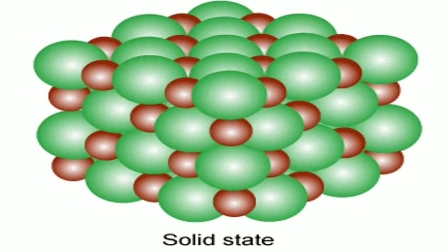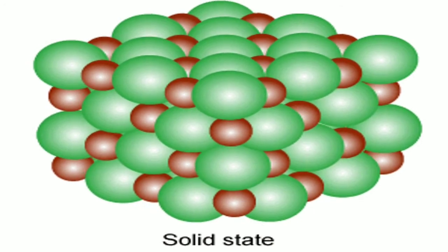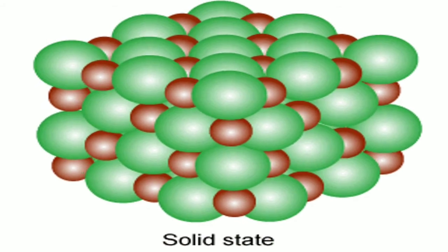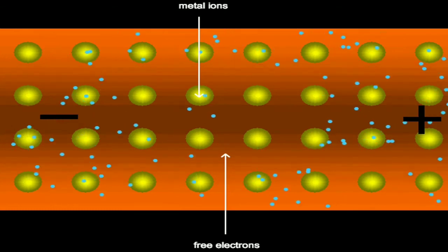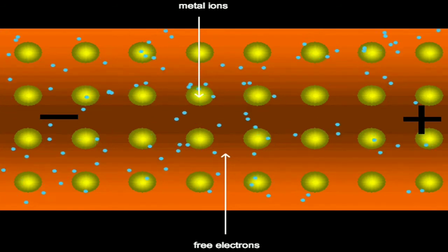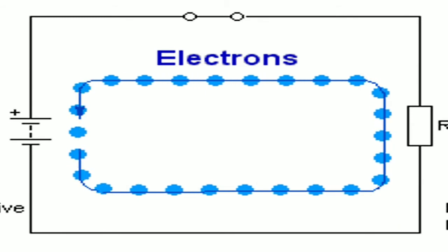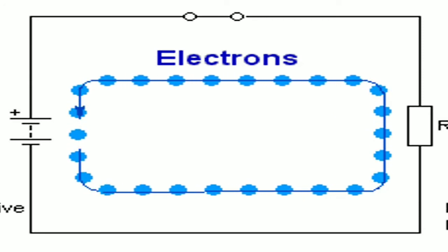Now we are going to discuss how the charges flow inside a solid conductor or a wire. The atoms in the solid are packed together with very little spacing between them. But the electrons are able to travel through a perfect solid crystal smoothly and easily as if in a vacuum. When a steady current flows through a conductor, the electrons in it move with a certain average drift speed, of the order of just 1 millimeter per second for a typical copper wire.